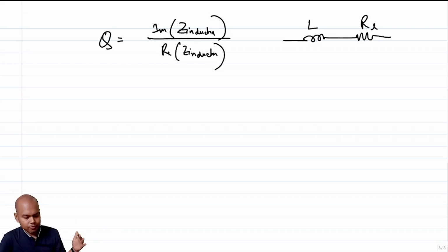So you have many other sources of losses, not only due to the current flow through the inductance, but it can go into the substrate, coupling losses and so on. So let's say I am able to lump all of them into RL, which is strictly not correct, but let's assume that at a particular frequency I am able to model it like that.